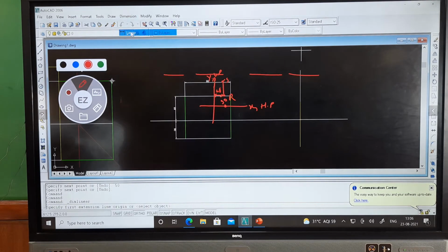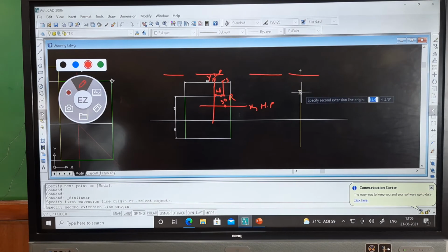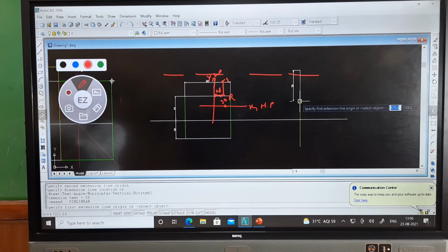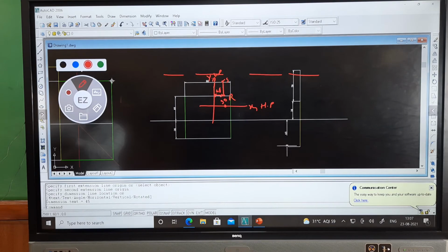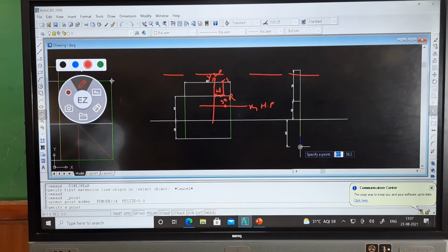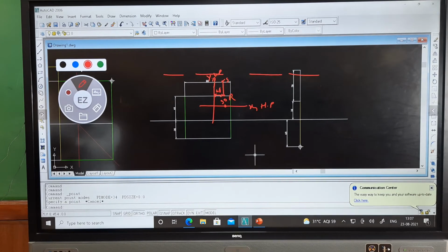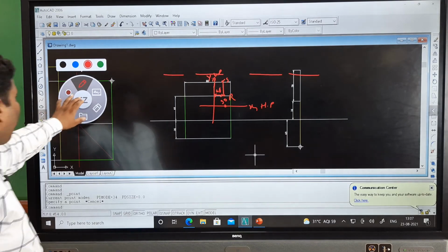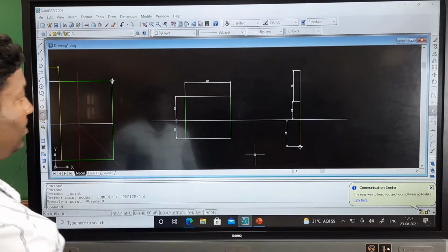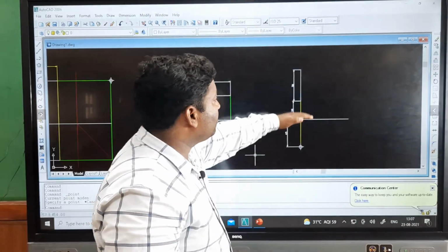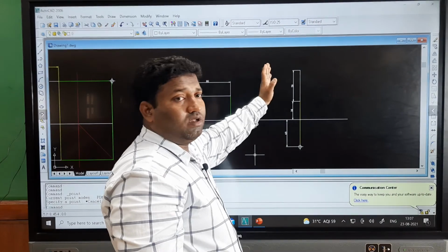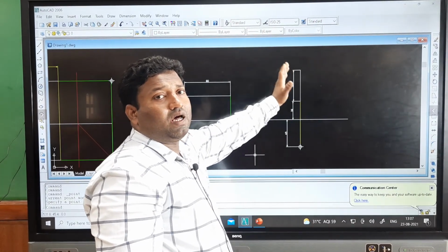From the dimension linear, 50 mm true length, 30 mm above the HP, 45 mm, and it is represented from the top view as a point. Finish. If you see, the line is in the first quadrant, 30 mm above the HP, and the line is parallel to the VP.